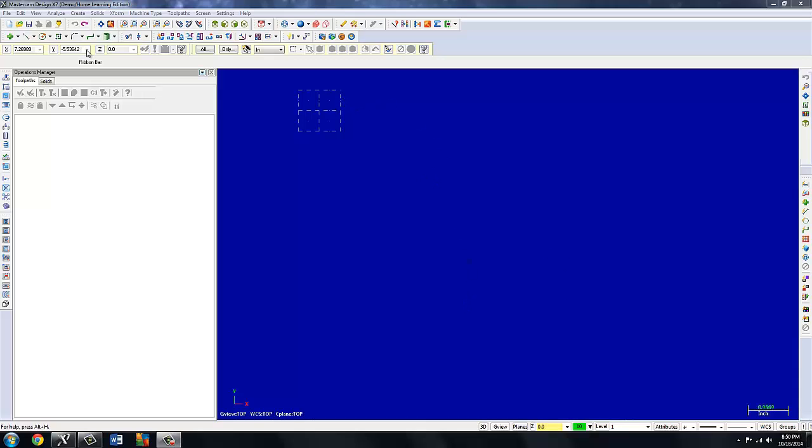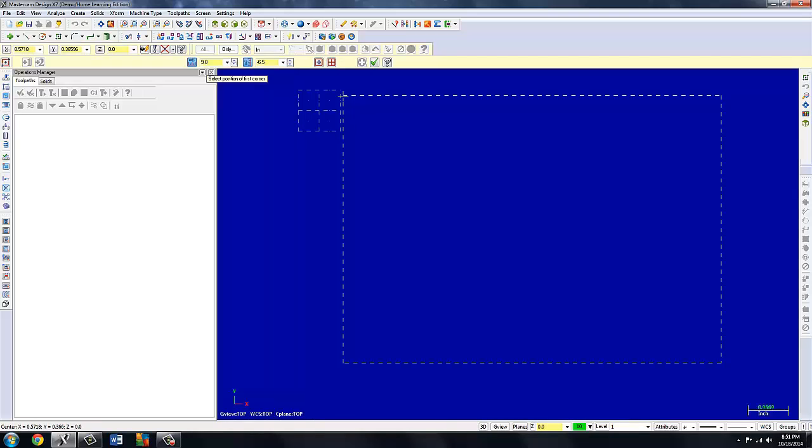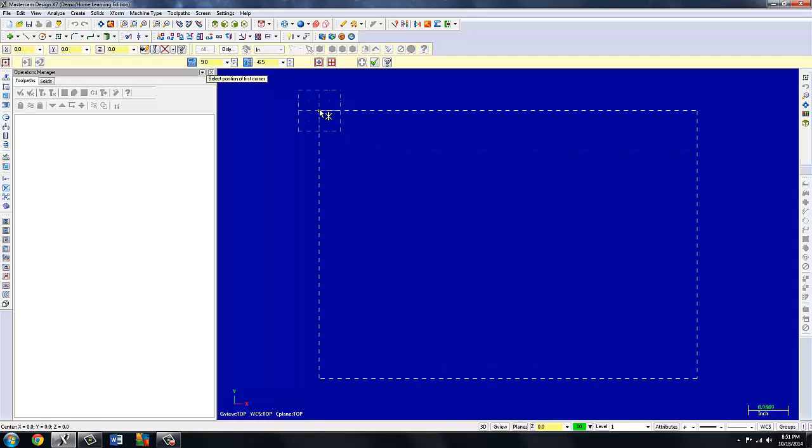To begin, however, I'm going to build the most obvious element, which is the rectangle. It's 9 by 6.5. That's a negative 6.5. You can't tell the origin on the print, but it reveals itself in the subsequent sketches on page 454. So I'm going to place that in the lower right corner of the origin and apply it.